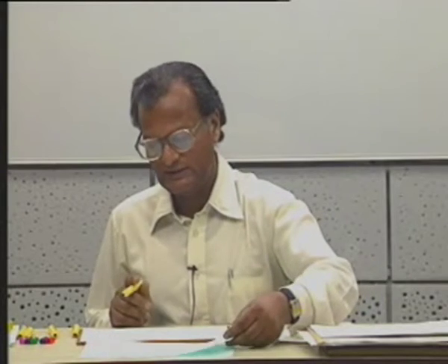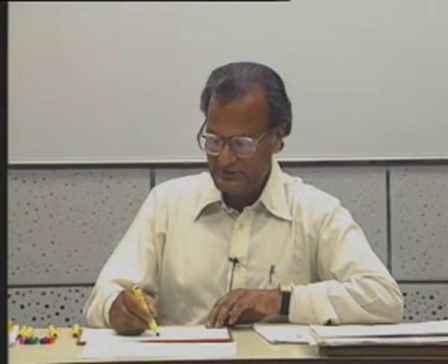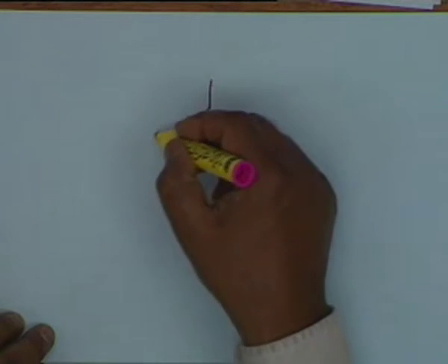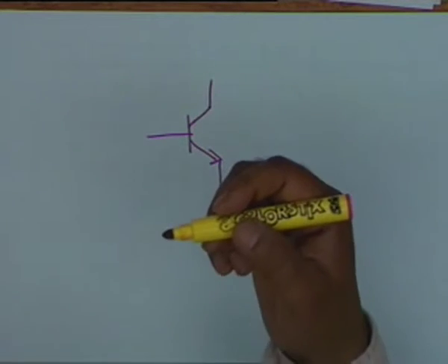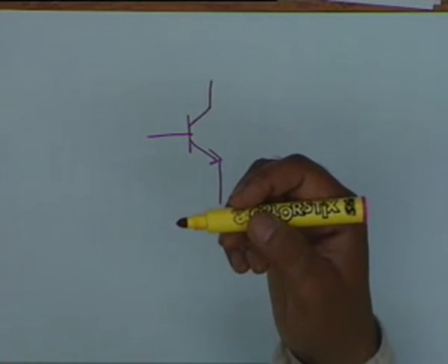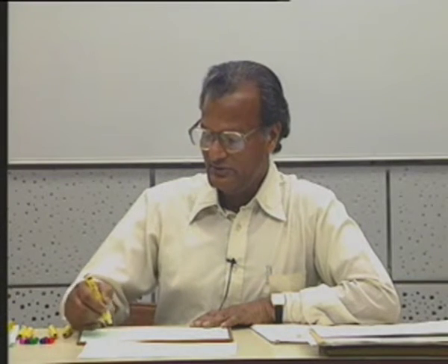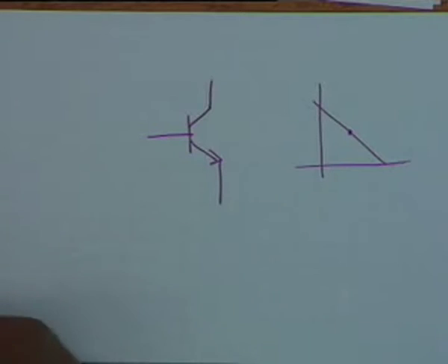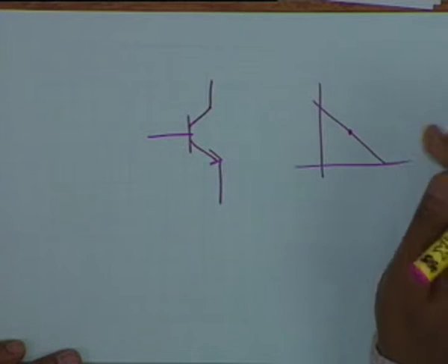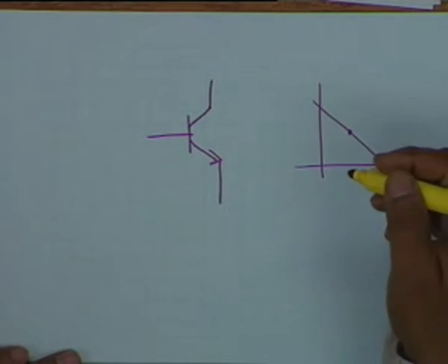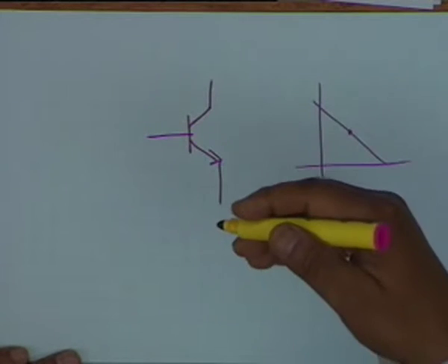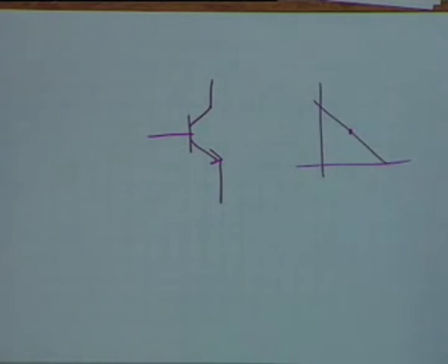Now let us look at a transistor, and for being specific, let us consider a common emitter transistor. Well, you know, we have to use DC, we have to use a power supply VCC, we have to use resistances to bias the transistor properly, and we have to determine a Q point at the middle of the load line to make maximum possible swing and all that. Now for maximum linearity also, the characteristics are maximally linear near the middle of the characteristic. At the saturation point or at the end they become curved. So let us say we have a Q point. Now we want to operate around this Q point.